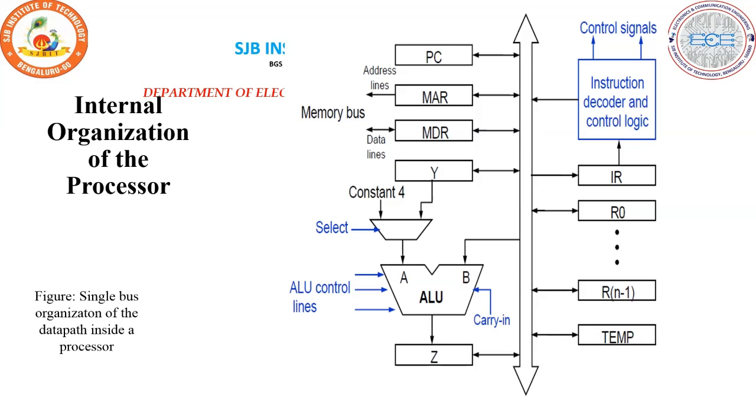and that is stored in the instruction register. The content of that particular memory location is stored in the instruction register. This keeps on repeating if the instruction occupies more than one word. Step one must be repeated as many times as necessary to fetch the complete instruction. These two steps are usually referred to as the fetch phase. And step 3, carrying out the action specified by the instruction in the IR, is considered the execution phase.